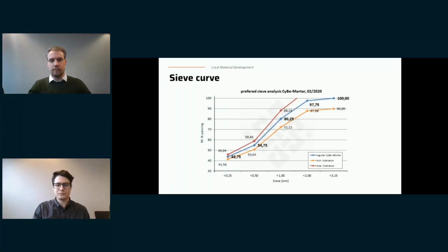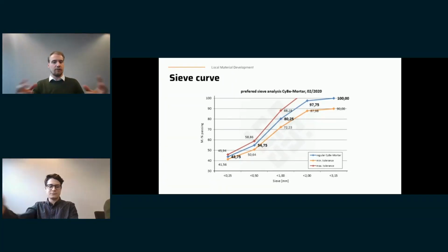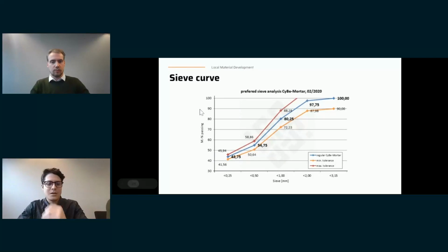Using this technology, you can easily adjust the lost formwork that we explained earlier to make that bigger or smaller to accommodate this different column size. This also means that, let's say you are planning to build up multiple stories or different weights in the roof, that you can easily change the one column to be a bit bigger and then another part of the building be a bit smaller without changing any formwork. Right, so it's more adaptable.